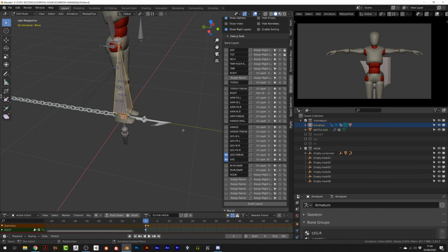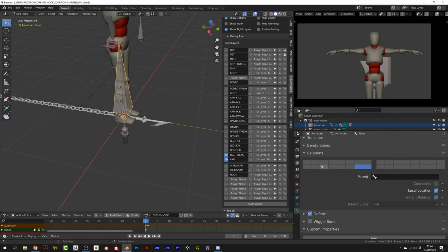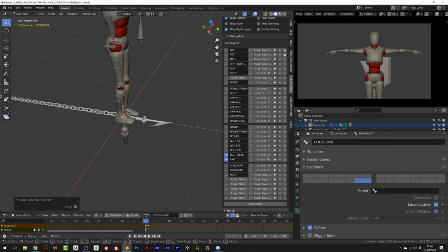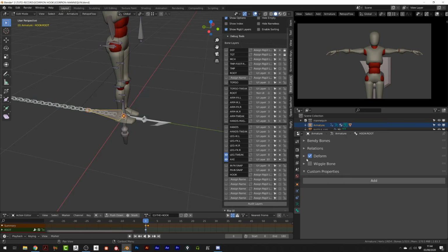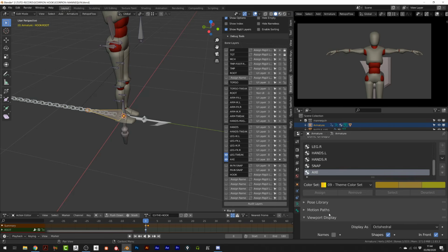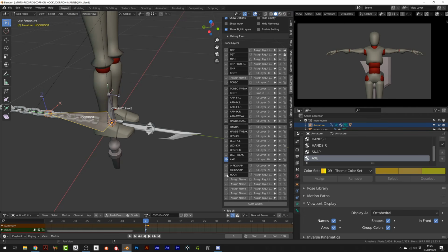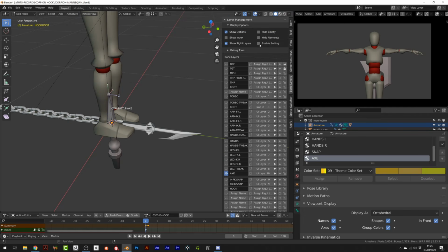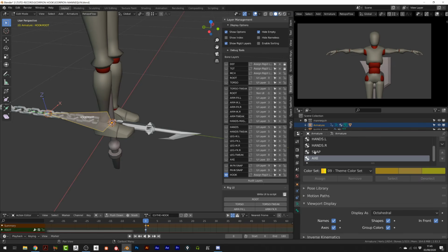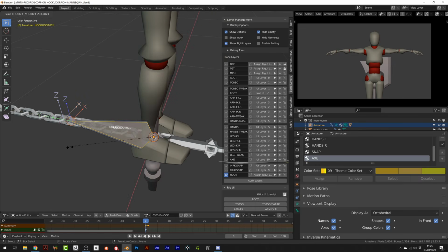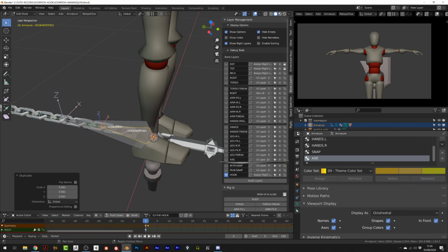And then I will create a separate bone per hook, or per empty, we have created just before. From there, I will simply parent each hook empty to the corresponding bone, so that I will be able to animate them alongside the armature, so into the action of the character, and the empties will follow, and so the chain and the hook will follow.